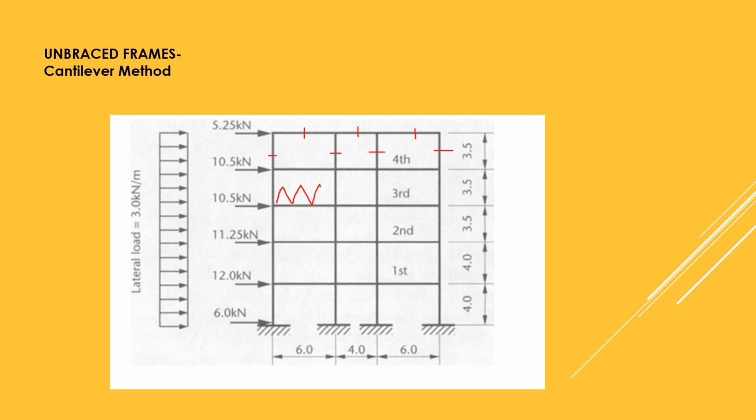We have to consider load patterns for each beam that we are analyzing and finally get the resulting shear force and bending moment diagrams, draw the envelopes for them, and take the maximum, minimum and those important parameters from these diagrams. So basically, this covers the basic aspects of manual structural analysis in concrete structure design.